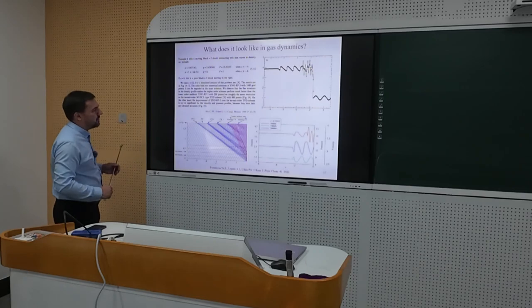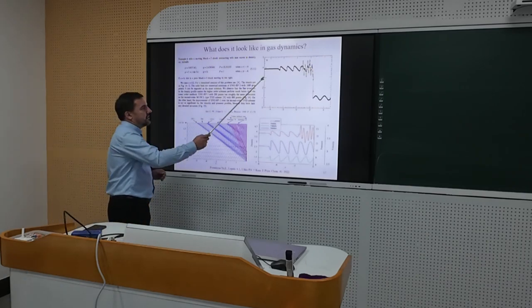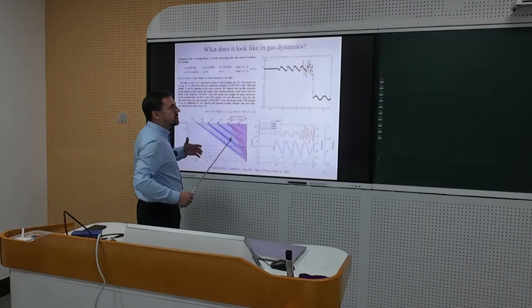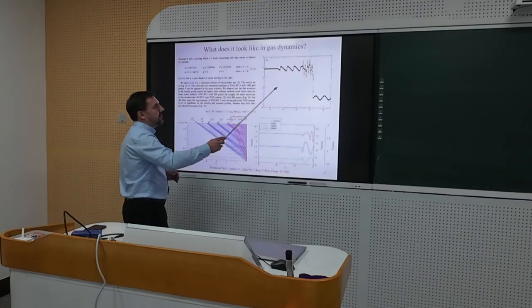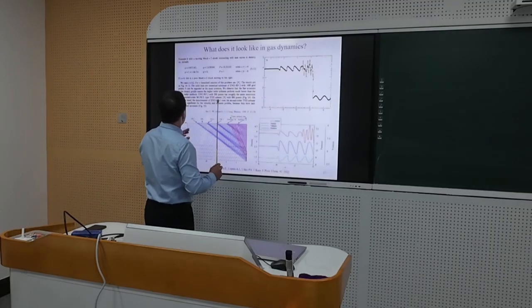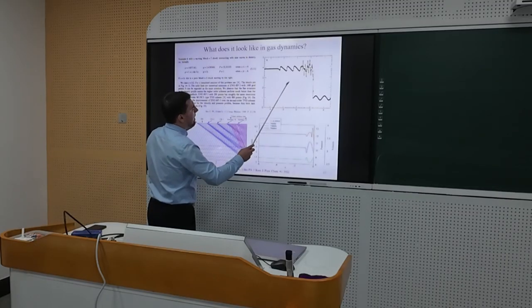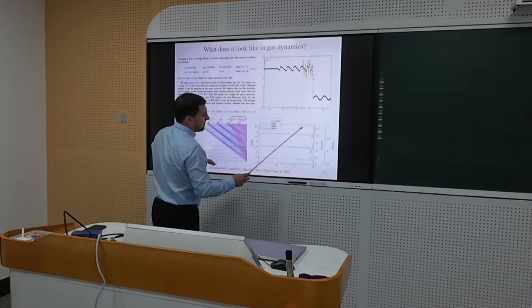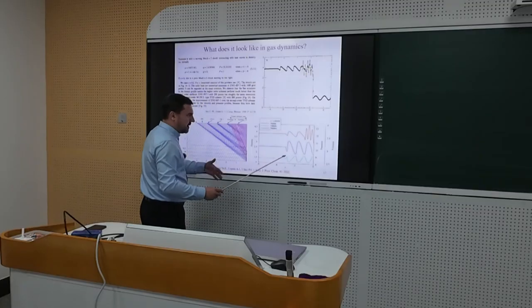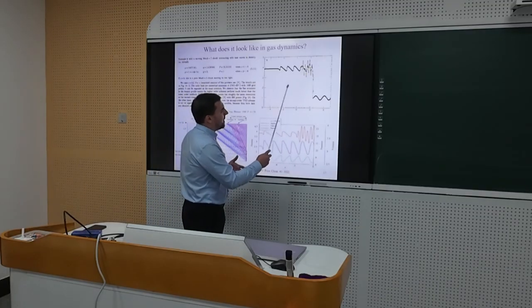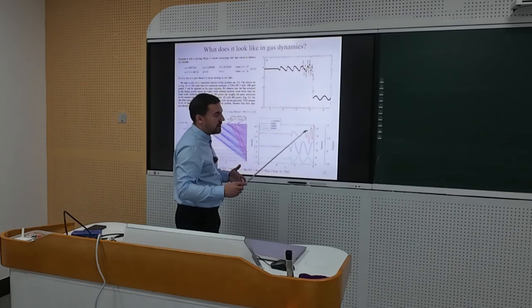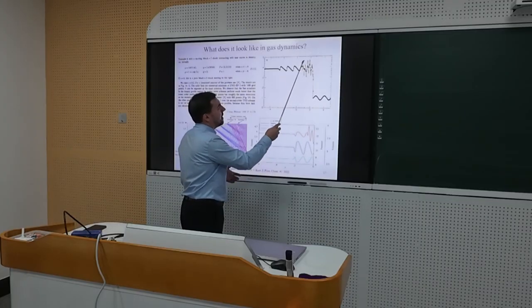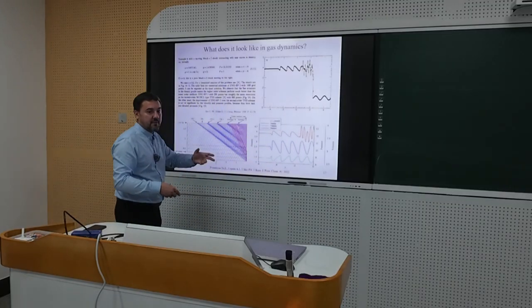We will also consider this paper one more time when we discuss numerical methods, because this is a very good test case showing that actually we need to use high order methods. These dots correspond to, I don't know, but it's a low accuracy order method. So the real solution includes this oscillation. It's not a numerical oscillation. This is a real response of your flow behind the shock wave to these disturbances in density. And the problem is that if you use a not high enough accurate numerical method, you will just lose all these amplitudes, pulsations, and that's it.